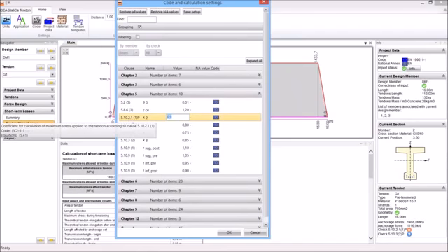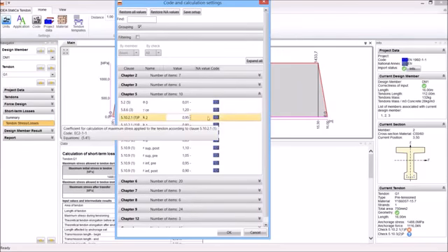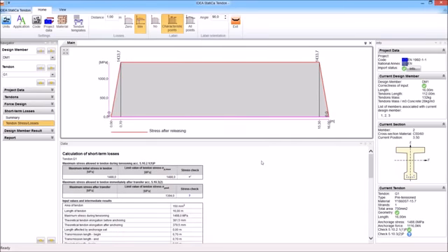You see 5.10.2.1, and we can improve it, increase it to 95%, which means that based on the Eurocode, you can do it in the case that you measure the stresses in the factory with certain precision. So in that case, we can go to a higher level of the stress, and you make your design more economic. Now we see that the check is okay.